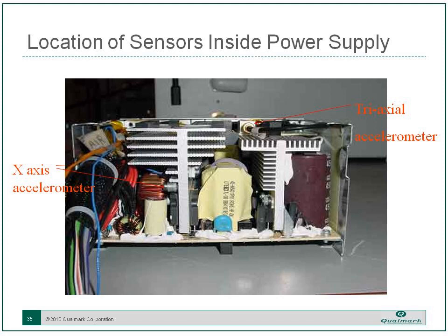And to get an idea of that effect, if we take a power supply, like we've been looking at before, and I put a triax accelerometer here so that we could get some measurements both here on a heat sink and here, and these were places where failures had occurred. So we were seeing breaks on these leads as one of the failure modes. Then looking at vibration transmission into this heat sink is a good thing to look at when we're trying to get a valid measurement for the stress the product is seeing.